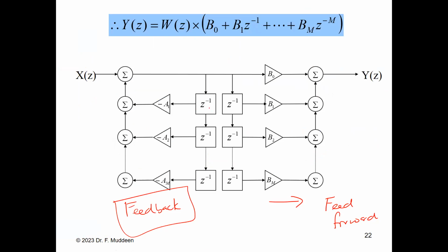I have inputs here. Sorry, I've swapped it on the other hand. I need storage for input, storage for input, storage for output, storage here. But notice now, the stores are now related to an internal variable WZ. Why store WZ twice? So in other words, by swapping the feed forward and the feedback, I now have double stores for the same value. So I could get rid of this. I could eliminate one of the stores.